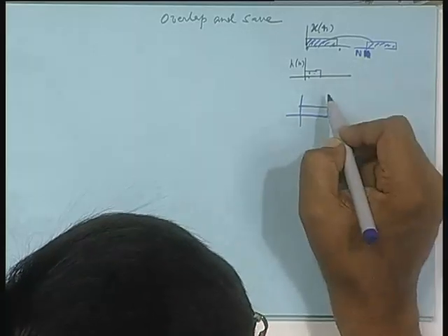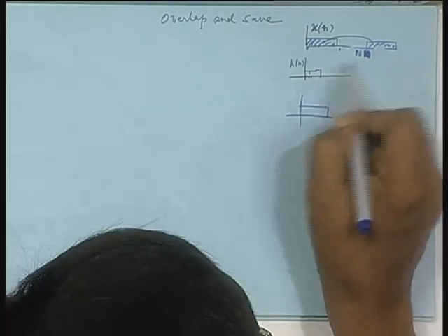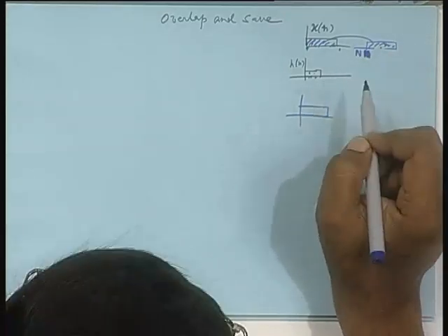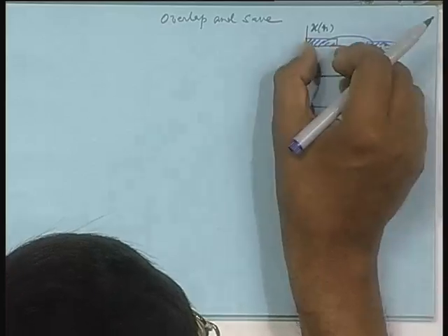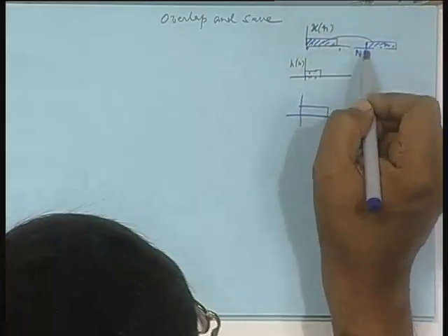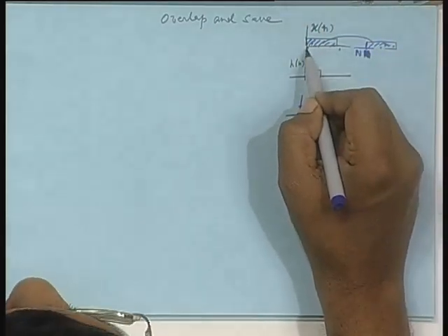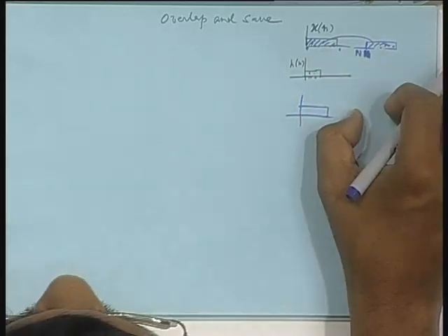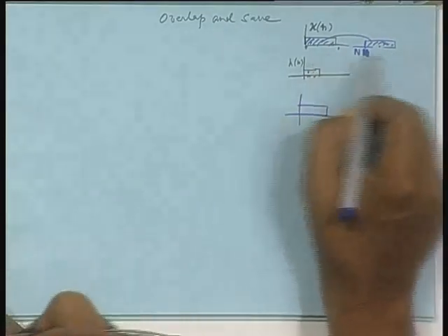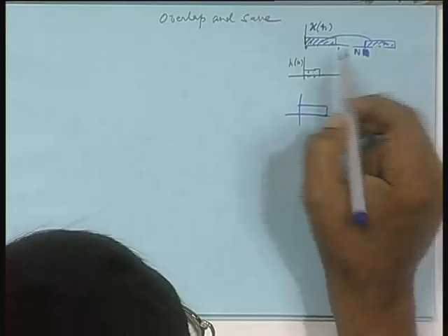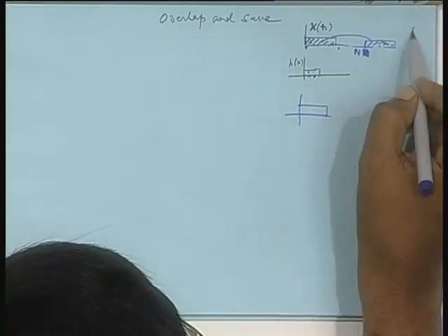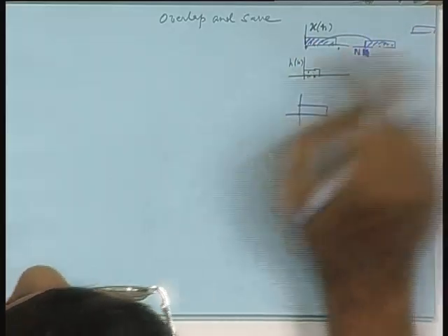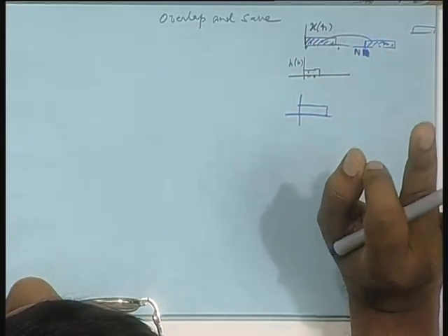Okay. So, conversely, if I am convolving two guys which are separated like this, then I can make life simpler by simply shifting it, aligning this with the origin. Convolve, calculate the output and again shift it back by capital N. So, next time I can convolve with some other segment here. I will again shift it back to the origin, convolve, get the result and again place the output there. This way I can do.